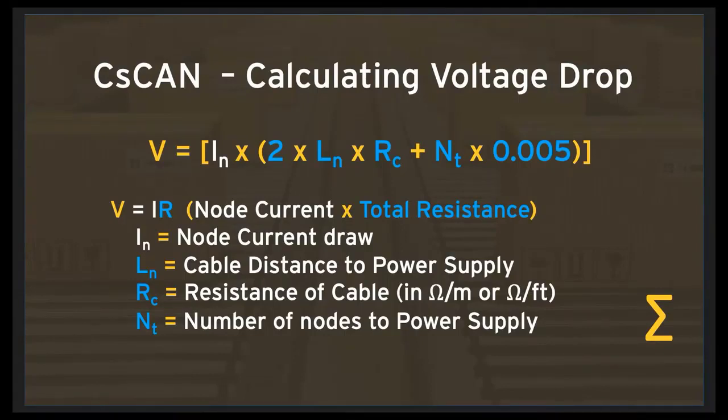And then we add to that what could end up being just another really small amount of resistance. And that is the fact that every time you break a network or you have a node on the network, the terminal block where you're connecting the 2 parts of the network has a little bit of resistance to it. And we're going to make an assumption that that's about 0.005 ohm. And again, we're talking about scenarios now where you've got a large network, and we're going to make sure we're doing this accurately.